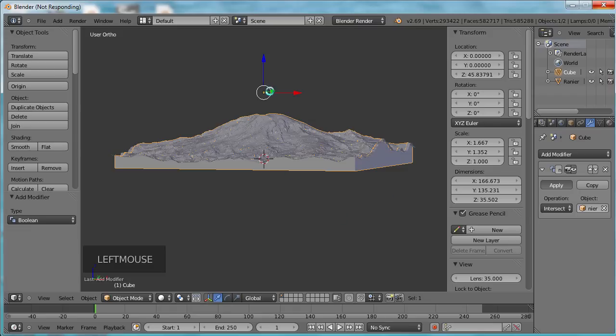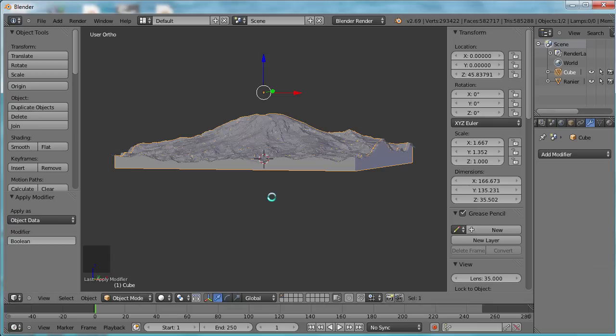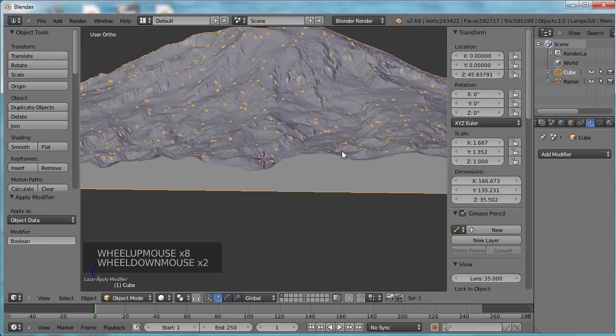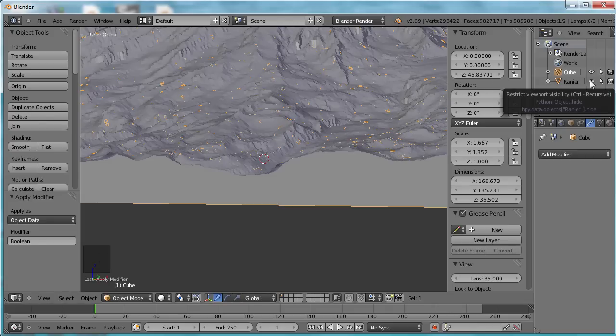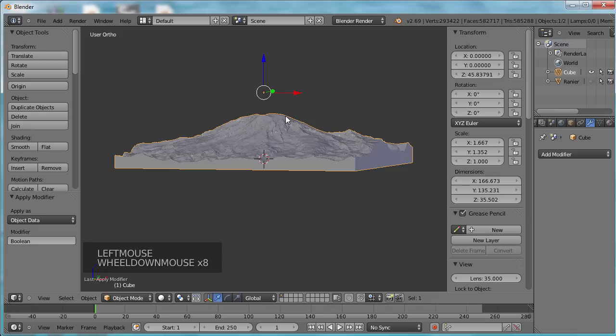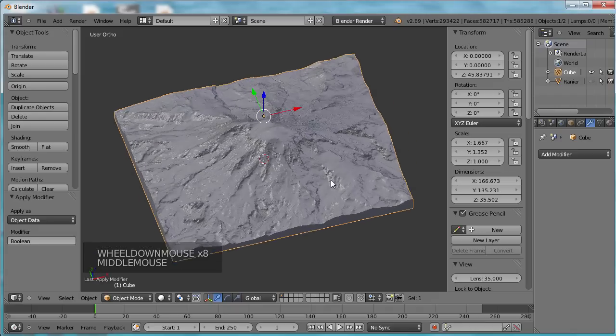And since this large mesh Boolean takes a couple of seconds to do, with the modifier on, we just want to apply it, do all the calculations once, and be done with it. But if you're working with a smaller model, you can leave your modifiers open and go back and change them when you want to. Okay, so it looks kind of funny and speckly like that. That's because the top skin is also on. If we turn that off, we can see that is our model.